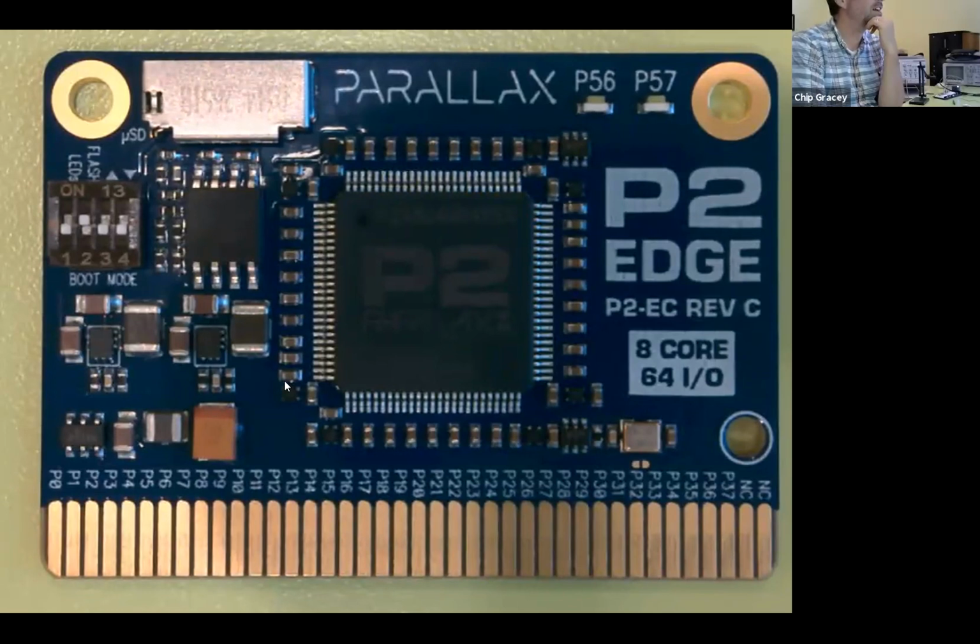So this thing feeds all these LDOs that drive all the IO pins. Also, it feeds these LEDs up here. Then this other switcher here is generating 1.8 volts. We were testing this yesterday under like some torture test at really high current load, and the thing varies by like maybe a millivolt. It's super consistent. It stays at 1.8 volts, and it delivers all the juice.